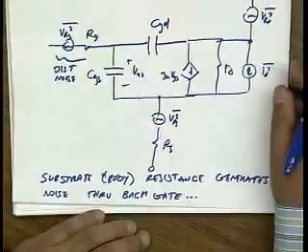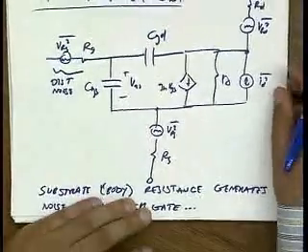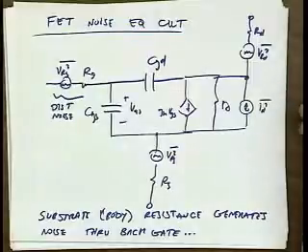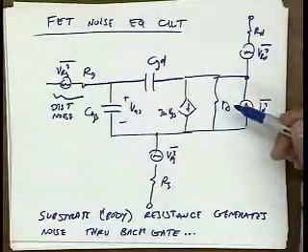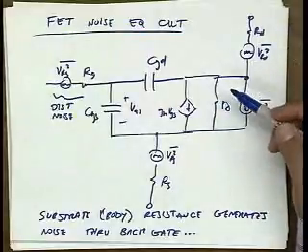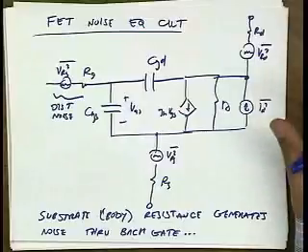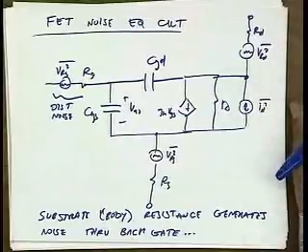But for now, the important point when you're doing noise analysis is to focus on the important noise sources, the dominant noise sources. Because noise analysis gets very messy very quickly if you include too many terms. It's much better to let a computer handle hundreds of different noise sources, and when you do your calculations, you should focus on the important noise sources. All right?